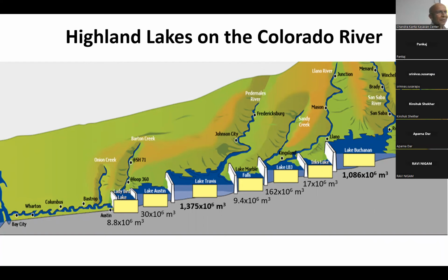When you build the dams and the reservoirs, it changed the hydrology completely, right? So we could not use any of the data before 1940, even though we had 45 years of older data. We couldn't use that because the lakes and the dams changed the hydrology. So we only had from 1940 to 2015, about 75, 76, or 77 years worth of data. I think 2016 probably, yeah.